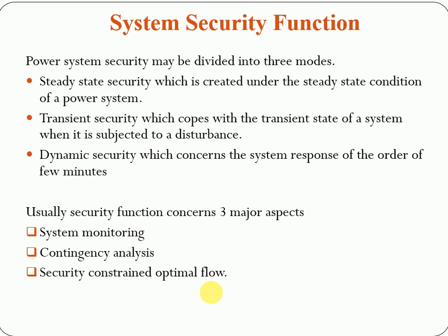The direct benefits of a modern SCADA system are constant access to a real-time picture of the entire network showing the power system voltage and frequency, supervision, monitoring, and control of power in real time, optimal operation of power system generation and associated minimum outage and faster restoration of the system in the event of grid disturbances, improvement in the quality of supply through better control of frequency, voltage and other parameters, and less dependence on basic telephone systems.